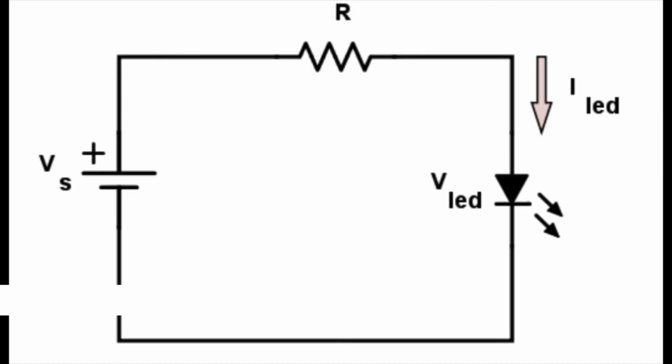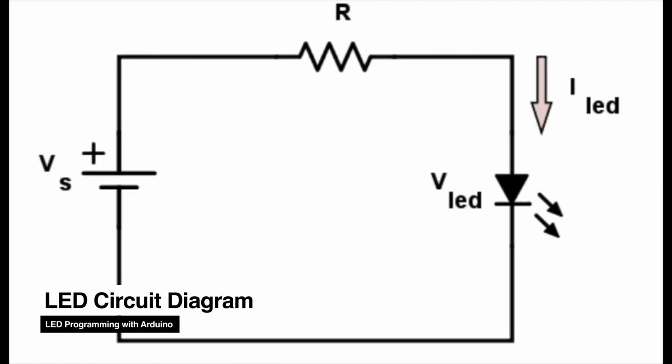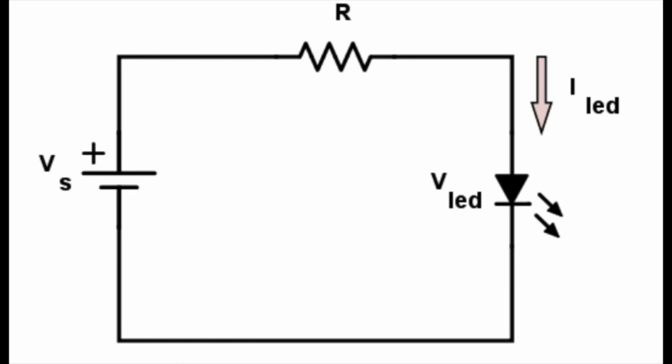Reading circuit diagrams is beyond the scope of this class, but it's good to know the basic diagram for an LED is as follows. This diagram shows the positive and negative poles on your power supply, the 2 flat lines, your resistor, the wavy V's, and the LED, shown as a diode, which is technically the D in LED, the triangle with the flat line.